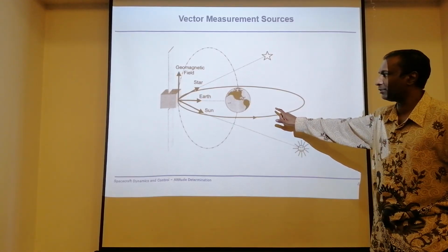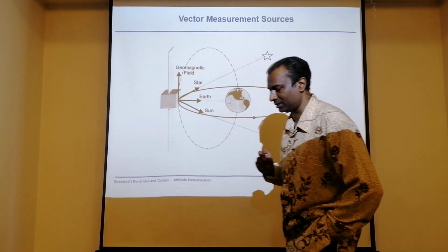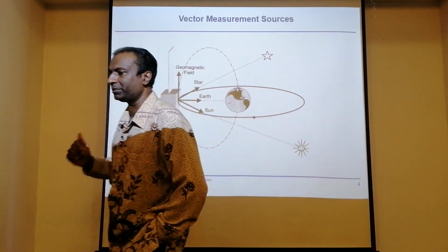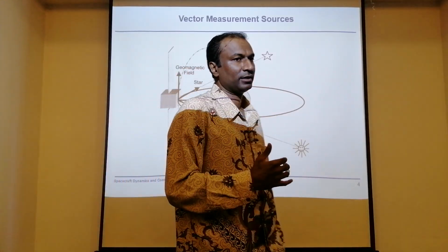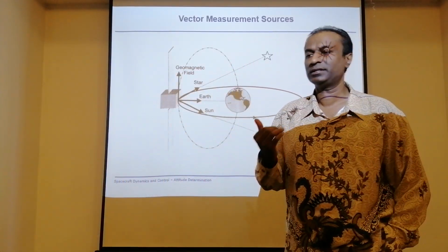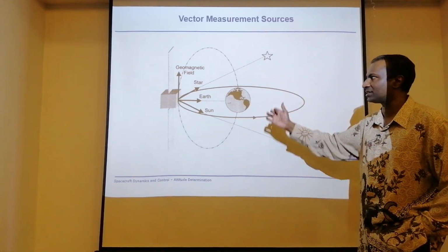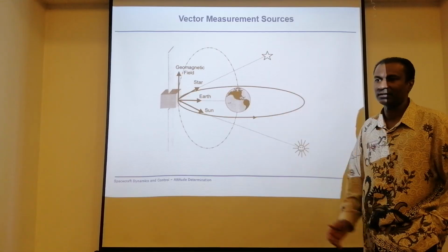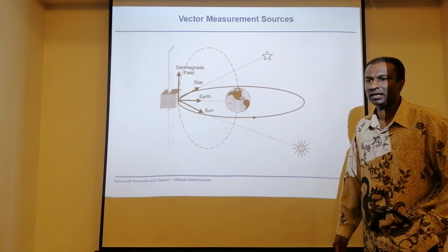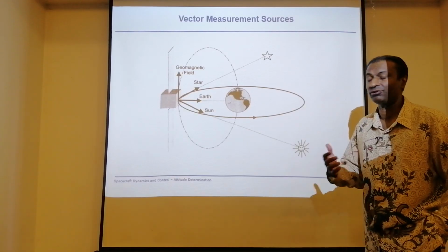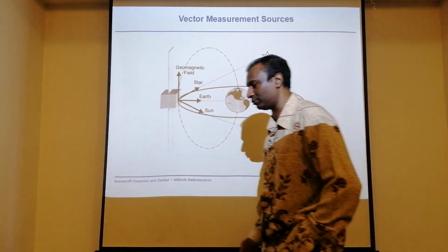We don't put anything related to the gyro here, because a gyro works on attitude rate, so it doesn't depend on an external source for information. That means it doesn't use the sun, a star, the geomagnetic field or planet Earth. With a gyro, you don't need any external indicators. It detects angular rate, and then from there you do an integration to find the attitude you want.